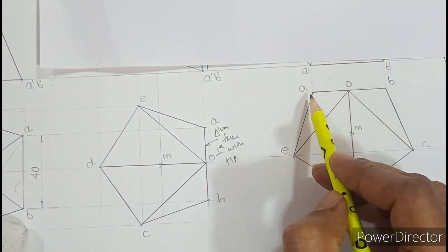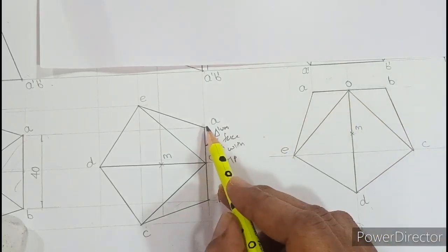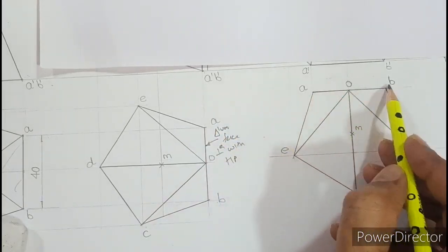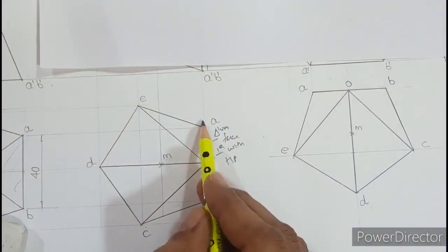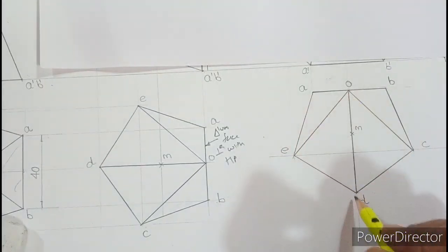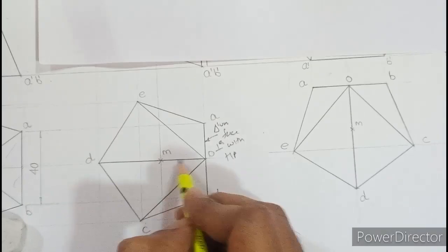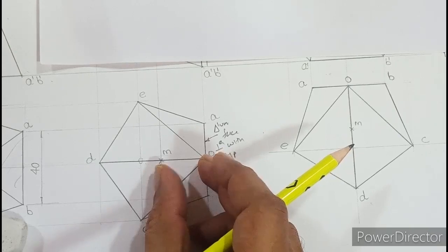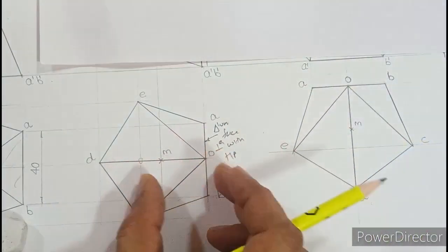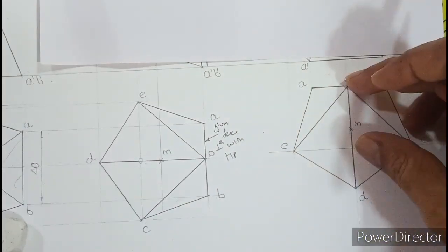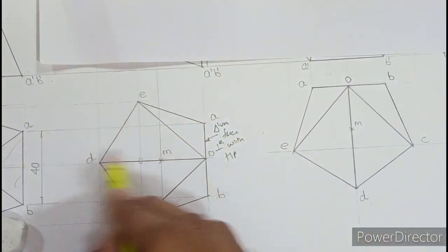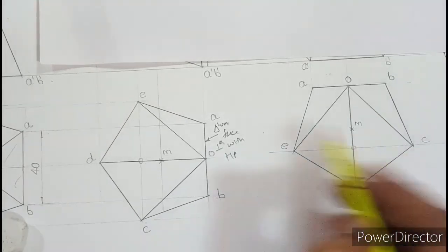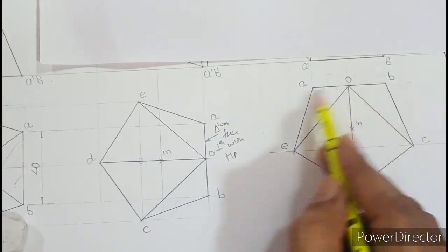Okay, so in the fifth diagram, this was our XY line. Any distance below XY you should first draw a horizontal line, and this A you have to mark arbitrarily anywhere. Then take A to O and O to B in the compass and transfer it. Now this line OD is perpendicular to AB, so draw a line OD perpendicular to AB. On this line OD, M will lie. So take O to M in the compass and transfer it here. Then take O to the circle that I marked and transfer it here. Now because OD and EC are perpendicular, with respect to OD, draw a perpendicular passing through the point marked by the circle. Take half of EC in the compass, cut on both sides and reproduce the same diagram.